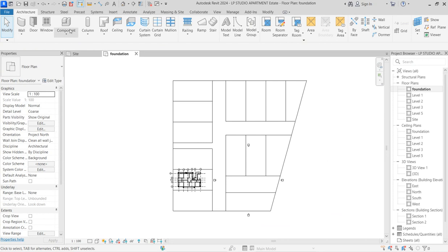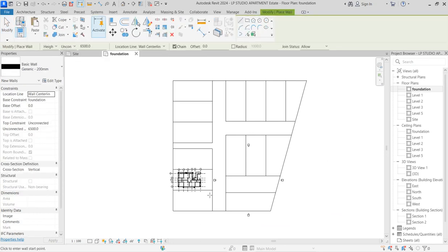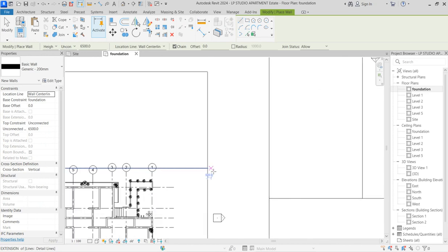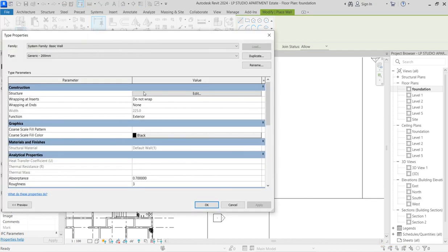At the foundation, you click on Wall. I'm clicking this one because I want to create the wall part for this. So what is the height of my wall? I'm reducing the height to something like 2500. Then the foundation, I may leave the color or change the color. So leave it the way it is.